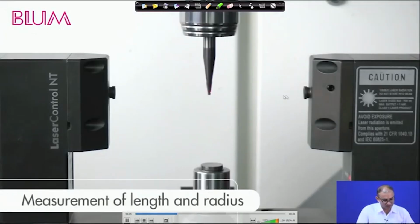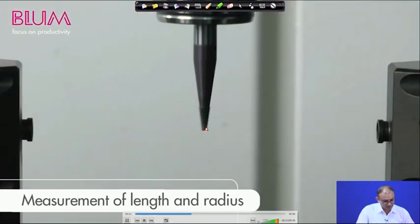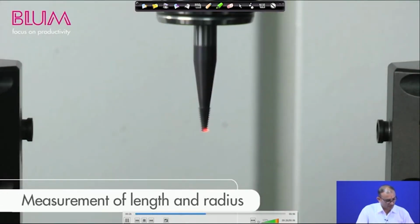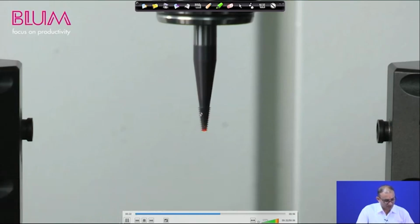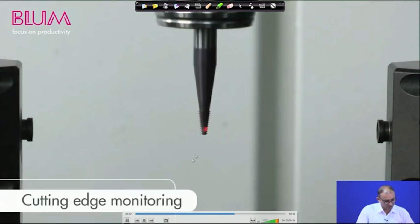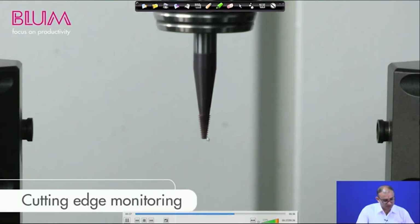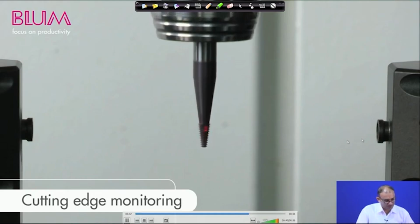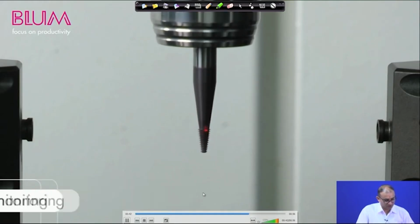So, the laser is coming from one location, and there is a receiver. When it touches this location, you can get the laser signal here, and then you find out the length and the radius measurement. Then, if it is going up and up continuously, you can also measure the teeth profile. So, for cutting edge monitoring, it goes one by one on the top surface, and based on this laser transfer from one location to the other, you will get the edge monitoring also.